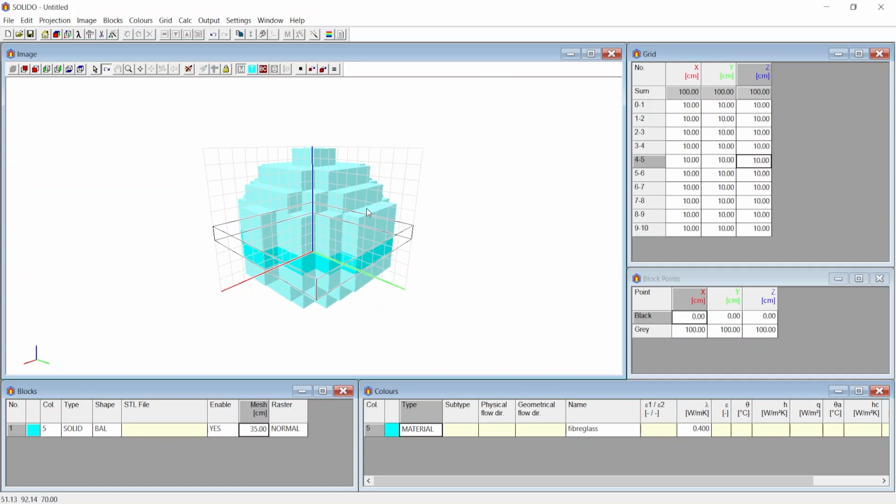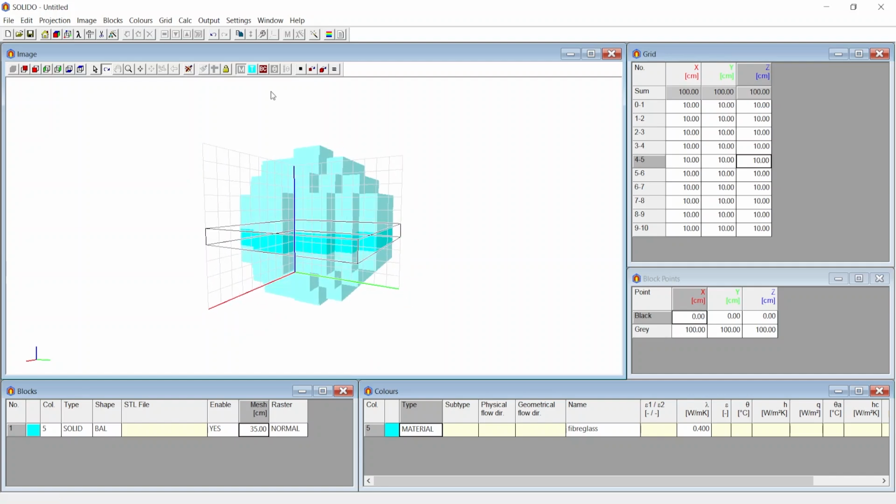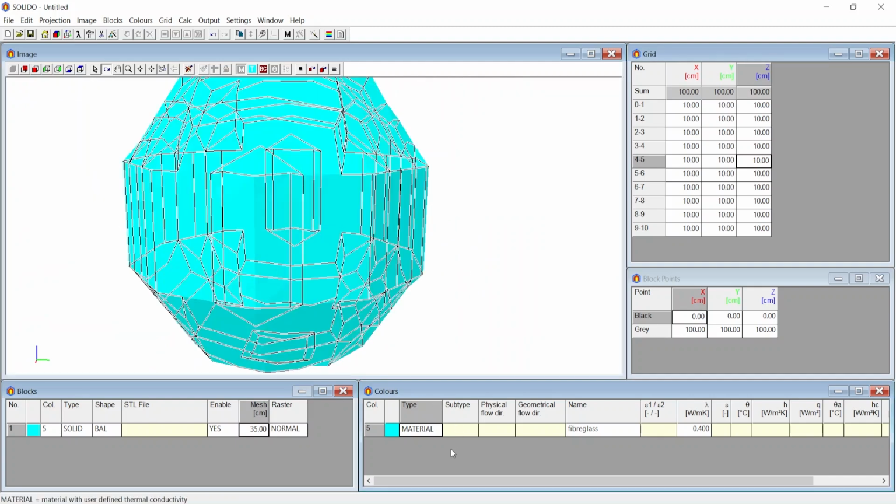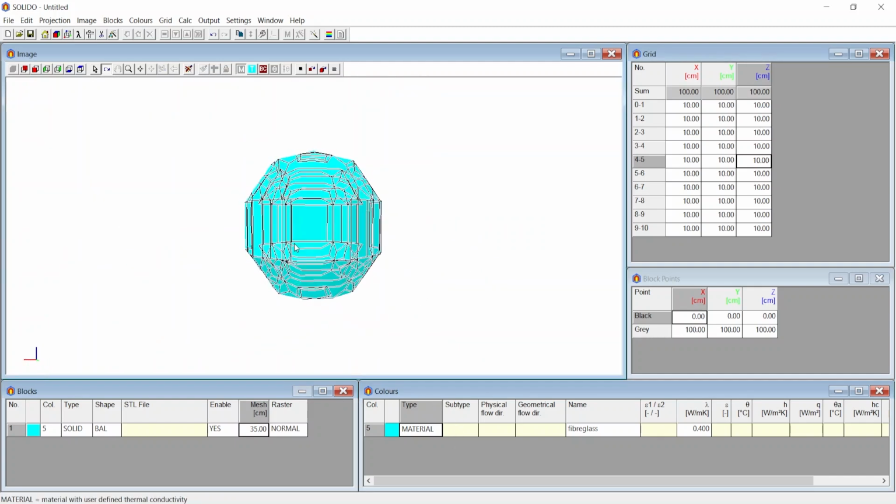Finally, the third step is to create a fitted object. Here the core of the geometry remains in a rectangular voxel framework, but on the surface level, we link it to the original geometry mesh. This creates a smooth hexahedron at the surface level by either adding or subtracting the rasterized geometry.